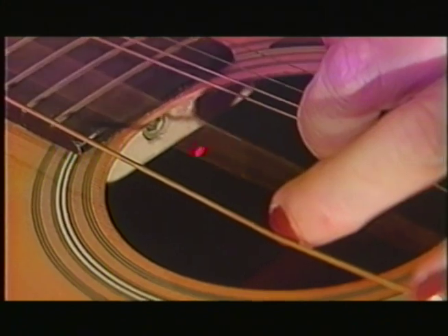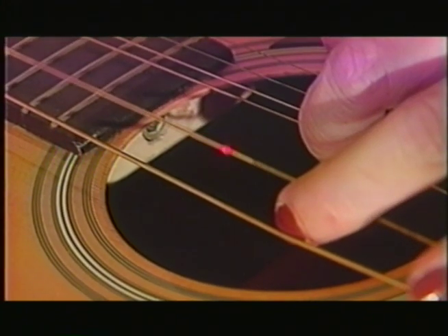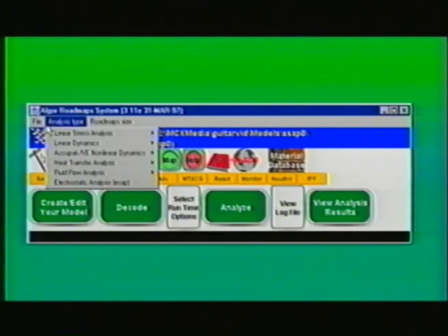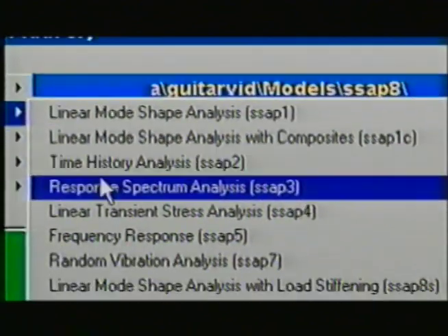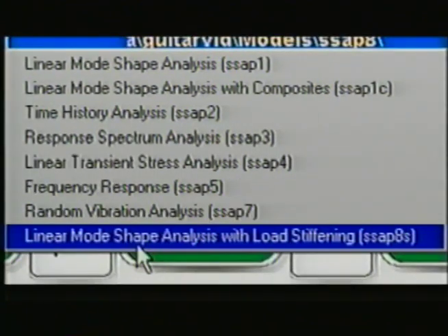In an airplane or car, loads or forces, and therefore natural frequencies, are constantly changing. Therefore, to predict the dynamic response, you must consider load stiffening. ALGOR offers two ways to predict frequencies as a result of load stiffening. The first way is with the vibration level 2 extender.